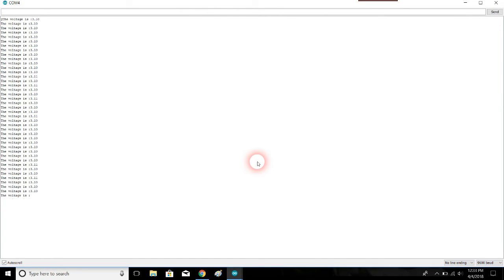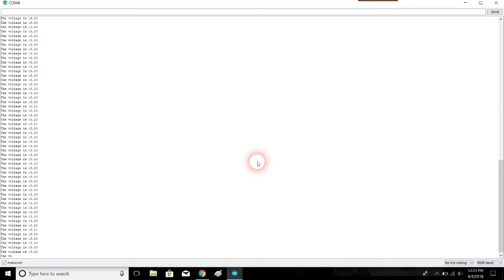All right, moment of truth, yet again. Hey, there we go. Looks like our math was a little off at some point though, right? 3.10, 3.11 volts rather than 3.4. That can probably be caused by the tolerance in the resistors.